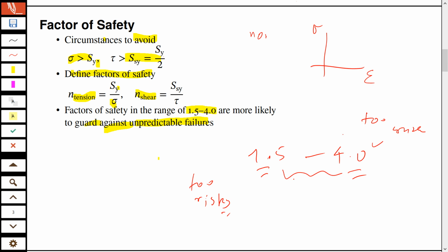Now, this choice will depend on your knowledge. For example, if you have used a material many times, and you know that 1.5 has worked for that, then go for that. But if you are trying something for the first time and have no experience with it, then you should go for the higher value. You get this now? Will you be able to select the right material and right stresses by using this factor of safety? Maybe you can go back, see some of the examples, and calculate this, just to see whether we are safe or not. You don't want to be on the margin.